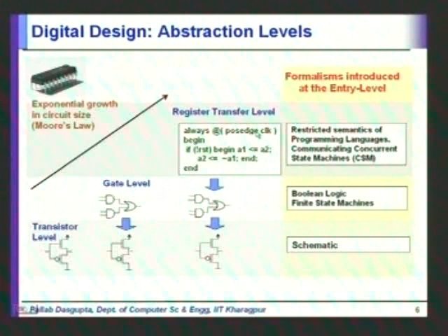So you can have, instead of posedge clock, posedge A, where A is a signal which is driven from another block, right? So by virtue of that, you can have synchronization between concurrent systems, and there are more, you can have sharing of variables between these systems. One is the output of one and the input of more than one of these blocks, right?